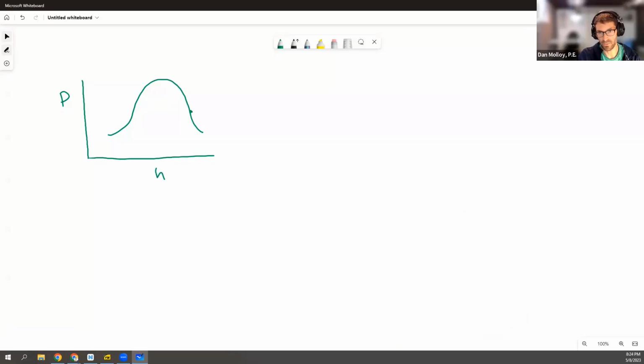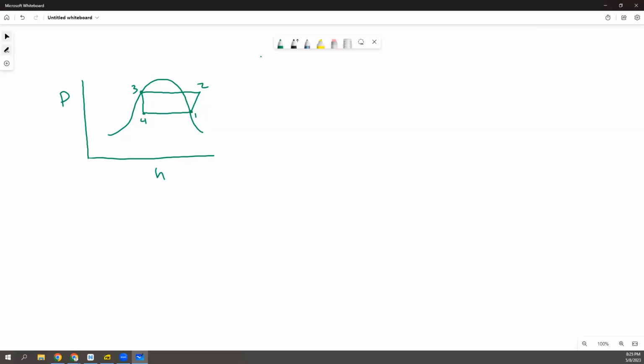Because normally when we draw the refrigeration cycle, we like to draw state one as being right on the saturation curve. But there's an assumption in that, isn't there? What's the assumption associated with selecting that point to be right there on the saturation curve? Right here. No superheat, no subcooling. No superheat for state one, and no subcooling on state three, the way you have it drawn. Exactly. Exactly.